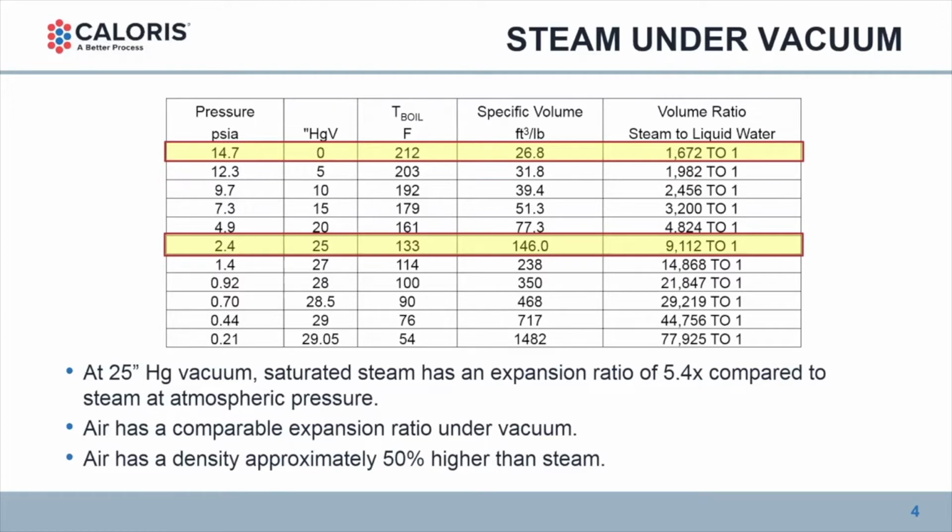There are a variety of reasons why we do that, but primarily in evaporators, we're trying to concentrate a solid rather than cook it. The example I like to use is whole eggs. We can concentrate whole eggs in an evaporator under vacuum. However, if you get that temperature up to about 120 degrees Fahrenheit, you're no longer just concentrating, you're cooking those eggs, and after a little while, you're going to get the hydroblaster out to get those scrambled eggs out of your evaporator.